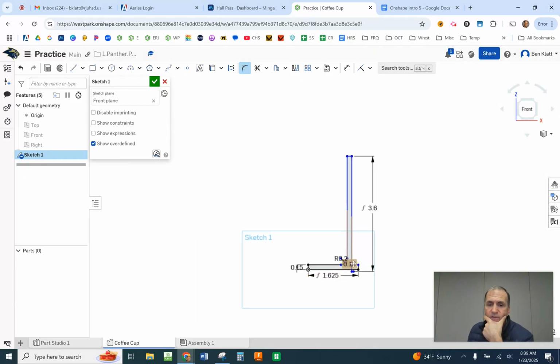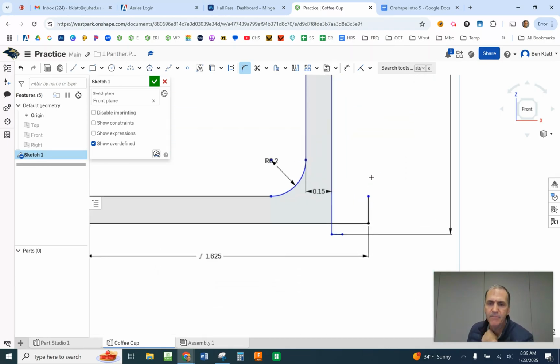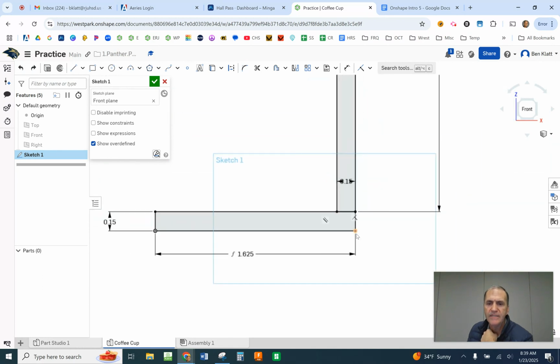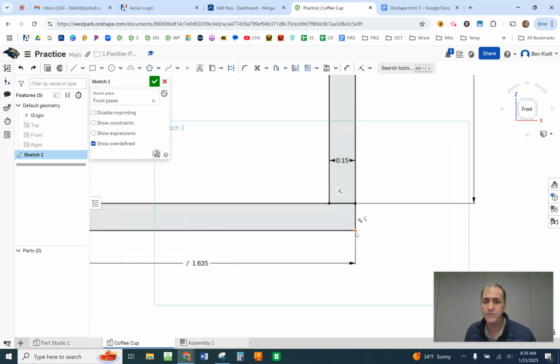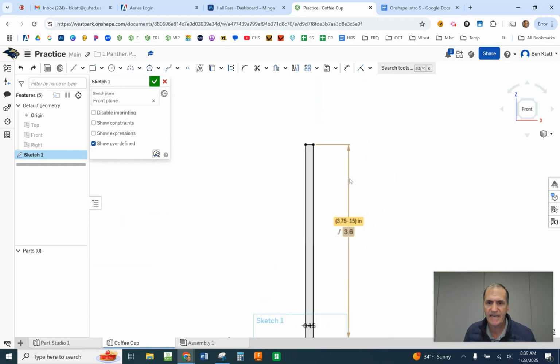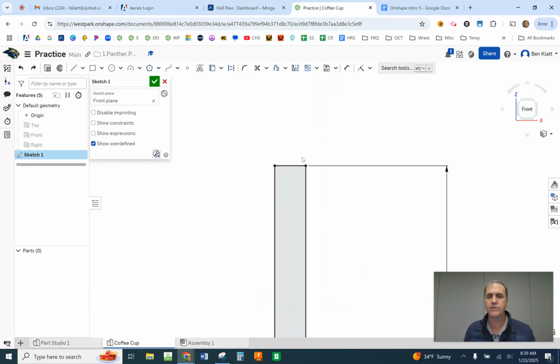We're learning things here. I often make mistakes in these videos, and I keep them in because it creates issues that you might run into. I'm going to undo that, undo that. We're going to do these edges to the solid. I always prefer to do it to the solid anyway, instead of to the sketch if I'm putting things like fillets and chamfers on. But let's go ahead and do this at the top.